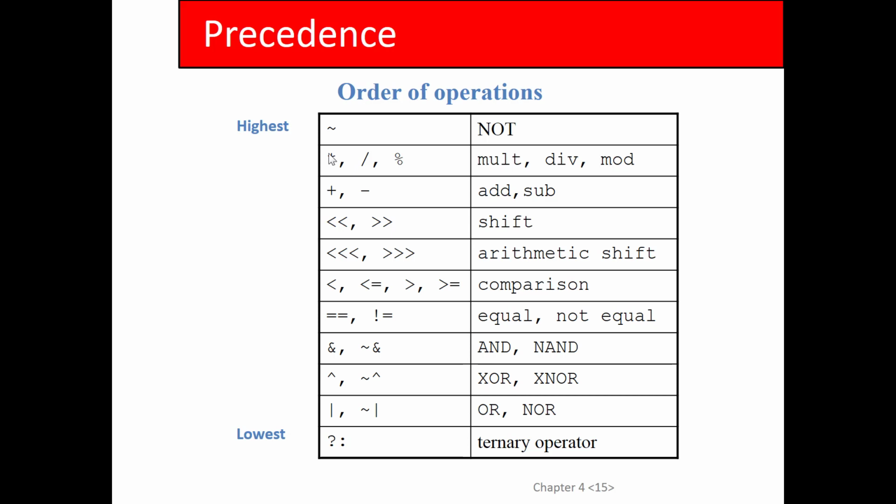Shift, this is also something that shift is in Java and C. You don't use it much in Java and C, but in Verilog it's much more common because in Verilog you're commonly doing bit twiddling, bit swizzling. There's different names for it. Bit twiddling means manipulating individual bits. For example, you've got a signal and you want to be able to take part of the bits and shift them this way and merge in other bits. So that's the shift operation.